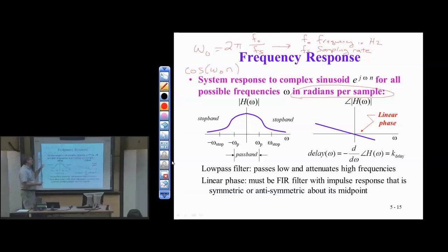All right, so this is our discrete time cosine, and we got there by sampling. So this frequency in continuous time F naught becomes this frequency omega naught in discrete time. So there's this formula, but I also know that this is going to be periodic with period 2 pi. So I know that eventually when F naught gets to be half Fs, omega naught takes some value. So what do I know? Through sampling, let's put it on the side.